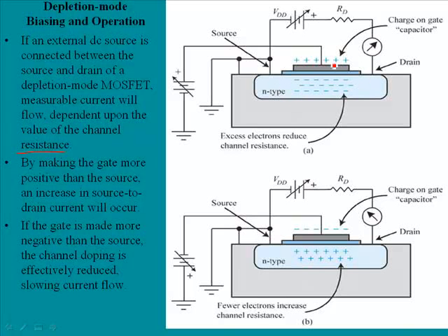Well, this acts as a capacitance, and the silicon dioxide, in effect, is the dielectric material, and the metal here is one side of the capacitor, and the N-type material is the other side. As we apply a positive voltage here, what will occur is that we'll have a positive charge on this side, we will have a negative on this side.